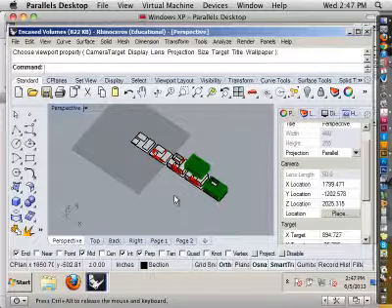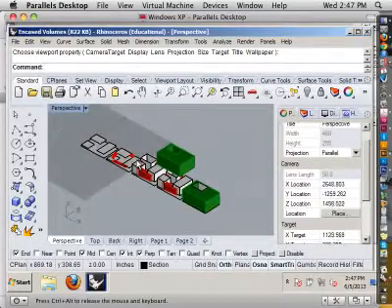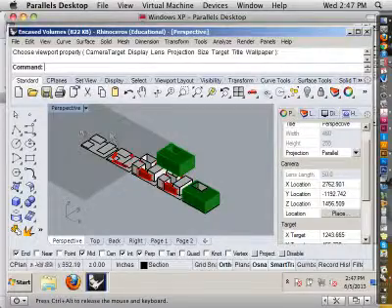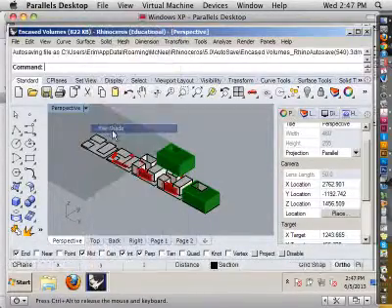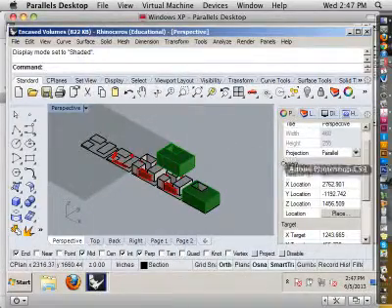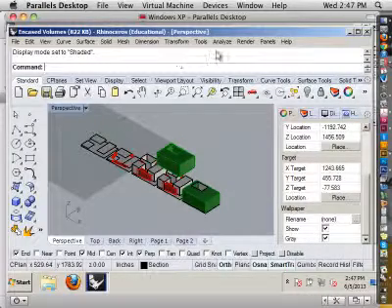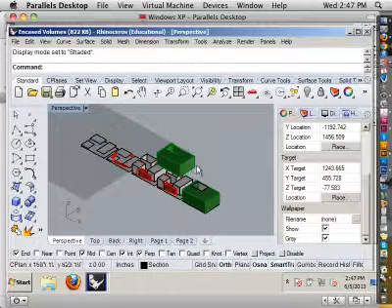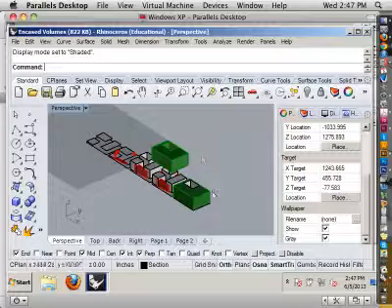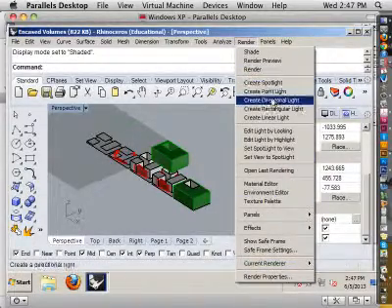So that's generally what you would do, and then it's a matter of doing Make 2D. I'm not sure if he wants these in wireframe or shaded or what. So you can go into shaded. If you want all of your objects to be white, I guess the best thing to do would be to export them as a rendering and then to also Make 2D them so that you can get the line work on top of them. So under render, you can turn on your sun. Under your panels, turn on the sun.